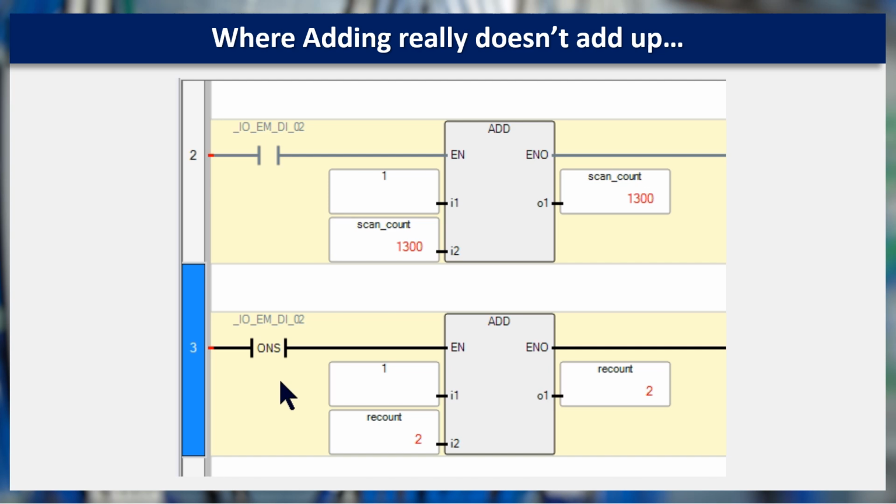From the amount of time it took me to push that button and release it, it counted 605 the first time, and then the second time was a little longer. Now I have 1300 in our count. So we cannot use the XIC instruction as a means of counting. We have to use a pulse instruction. But fortunately, we don't have to worry about this. Let's take a look at our actual counter.